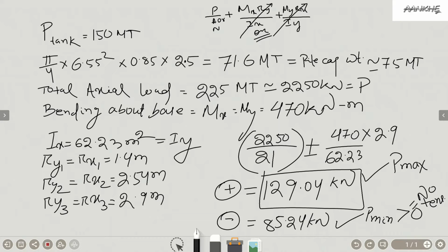Again, I would like to add, many geotechnical engineers will not be in line with my assumption, but generally I considered it during my designs. Now in all these loads, this is the tank load and this is the cap load. So where does the pile load, that is the self weight of pile, go?